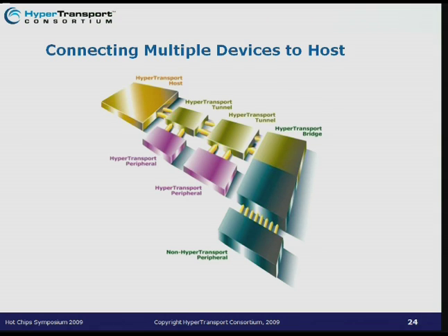And those tunnels not only tunnel packets to the appropriate destination, but if the destination is one of those tunnels, they are able to capture that packet and then send it to a corresponding attached peripheral device. Not only can we attach multiple peripheral devices in this chained way to a single host, but we can also bridge to other technologies, like for instance PCI Express,